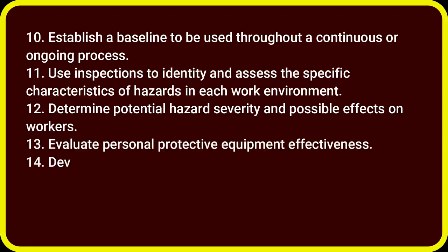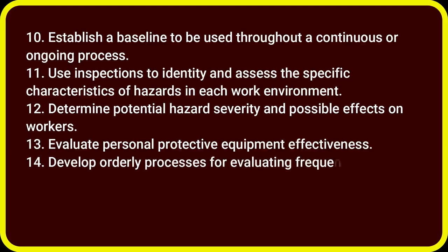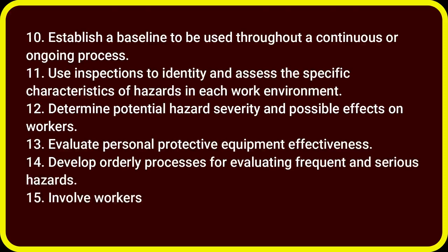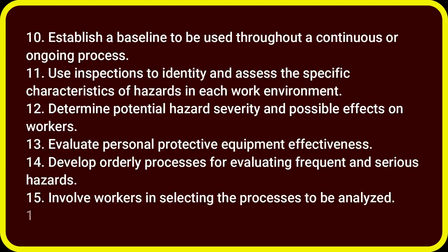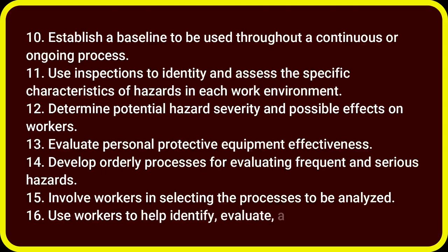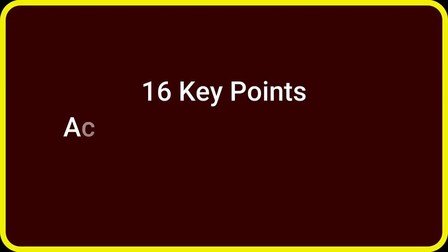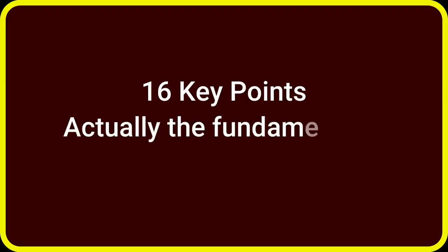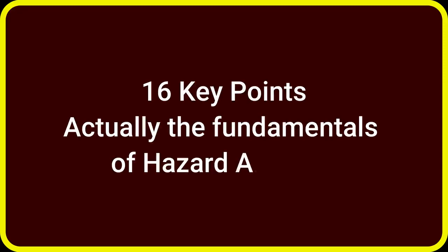Number 14. Develop orderly processes for evaluating frequent and serious hazards. Number 15. Involve workers in selecting the processes to be analyzed. And number 16. Use workers to help identify, evaluate, and correct hazards. Dear friends and fellows, these are the 16 key points. These are actually the fundamentals of hazard analysis.